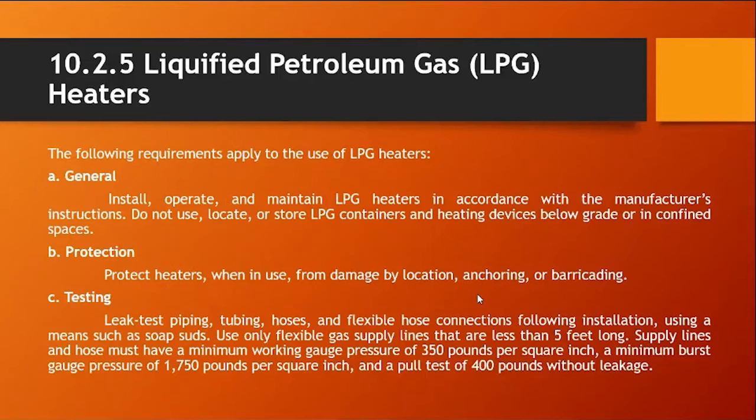Next is protection: protect heaters when in use from damage by location, anchoring, and barricading. Next is testing: leak test piping, tubing, hoses, and flexible hose connections following installation using a means such as soap suds. Use only flexible gas supply lines that are less than 5 feet long.